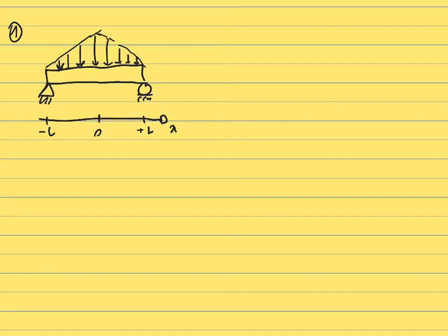Next we are going to identify the unknowns. In this case you have a pin. The pin at the point A can have potentially two unknowns, a vertical force VA and a longitudinal force NA. This force NA will turn out to be 0 in this case.